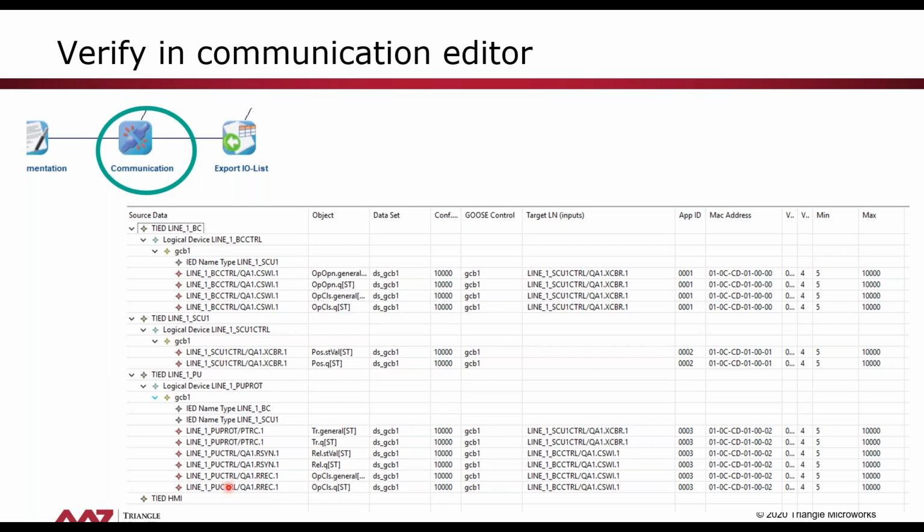And then we see, as an example here, the tool created a GOOSE control block here in the bay controller with those signals that are put in the GOOSE message. It created another GOOSE control block in the switch control unit. We also see here who is the receiver of the signals.